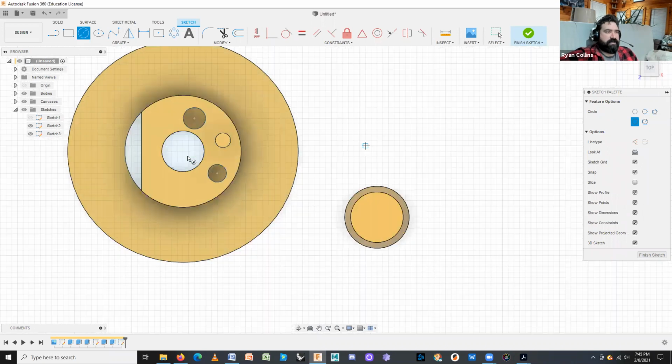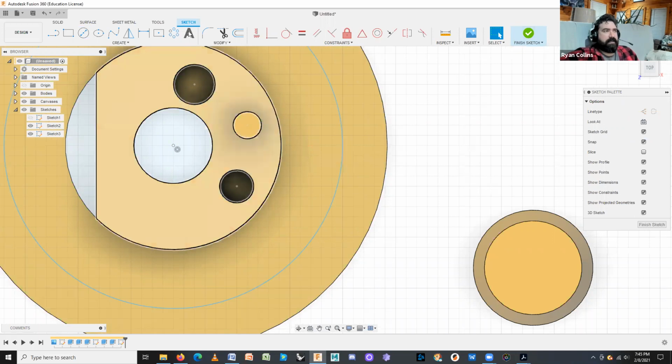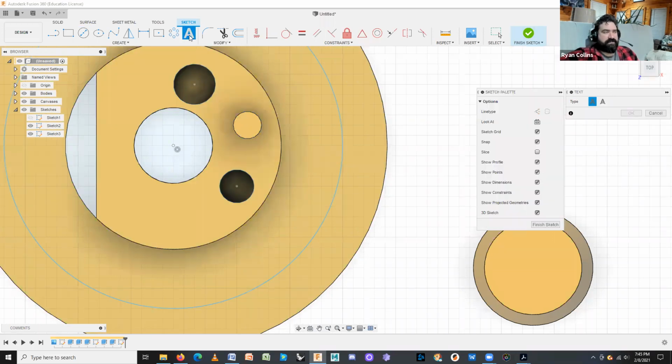I'm going to view straight down. Now there's no sketch showing from the previous sketches, but when I have my center circle tool selected and I select my mouse close to where the center of that main circle is, you see the concentric constraint pop up. Now I know it's going to be centered within the circle. I drag out, yeah, 16 looks good. Okay, that's what I wanted. I'm not finished with the sketch. I'm just finished with the circle. Press enter, we're done.